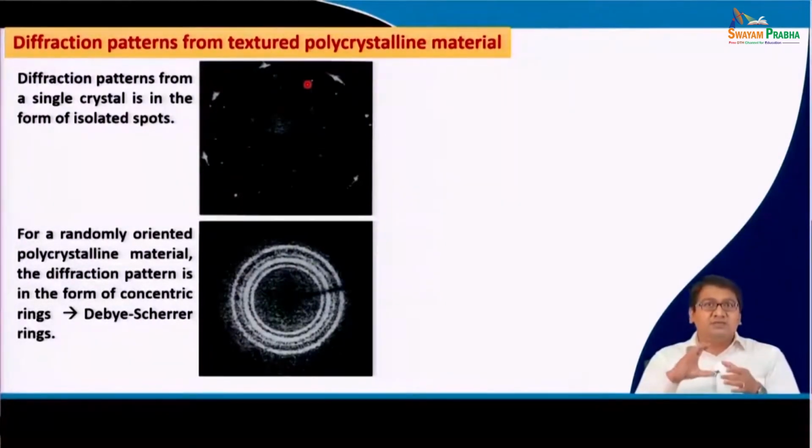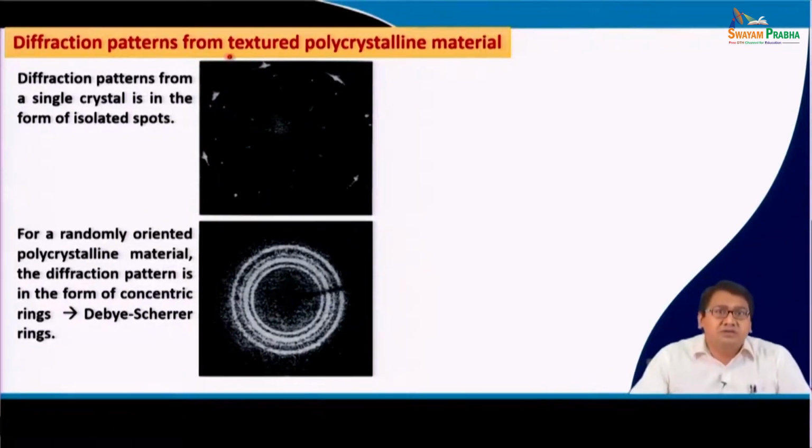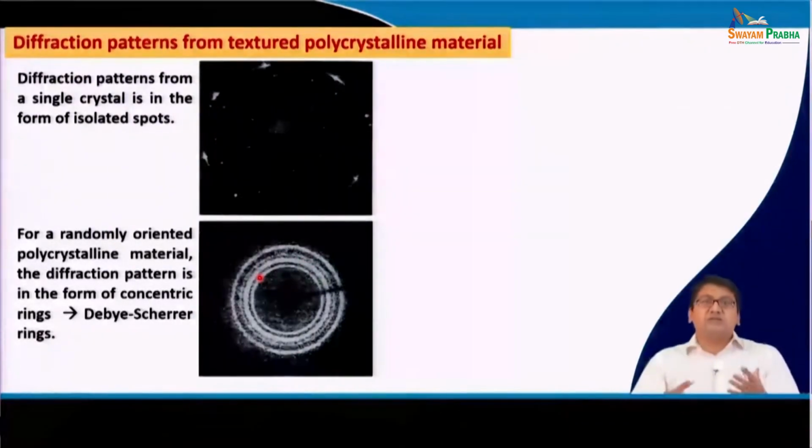Then let us put that powder in a certain X-ray transparent box and do the diffraction using X-ray or electron microscopy, and you see that we will obtain Debye-Scherrer rings, and these Debye-Scherrer rings will form concentric circles like this of the same intensity. You see 1, 2, 3, 4 different concentric circles have formed with the same intensity.